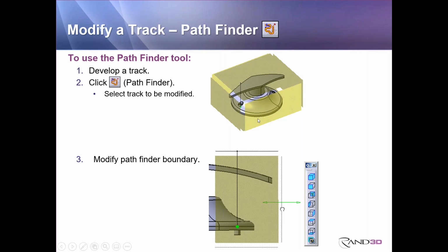You adjust those by left clicking and dragging those faces. Now, sometimes seeing a 3D environment on a 2D computer screen leads to some optical illusions. So in adjusting the bounding box, you might want to use your quick views. Maybe look at it from a side view and then drag that in, or a top view might make it a little bit easier. But again, you're going to readjust that bounding box.